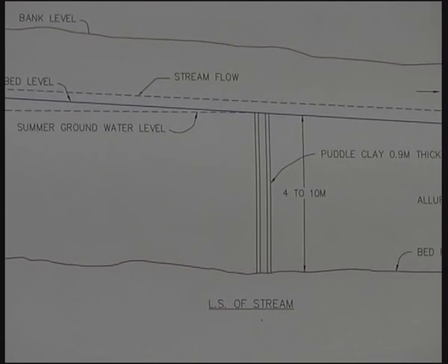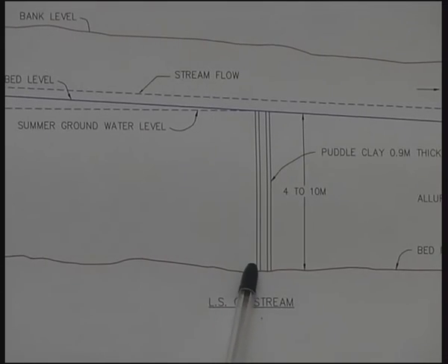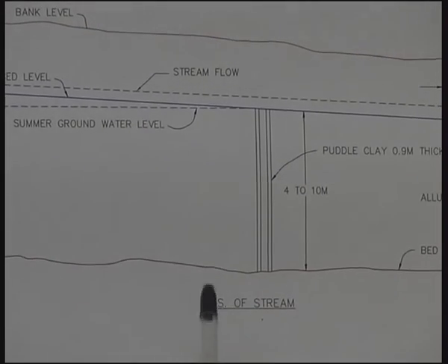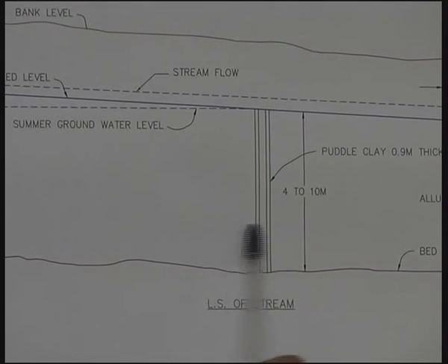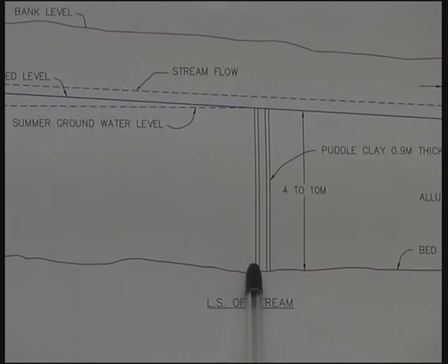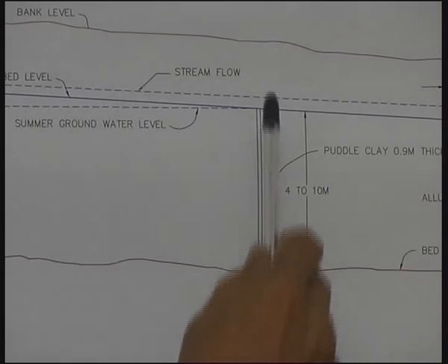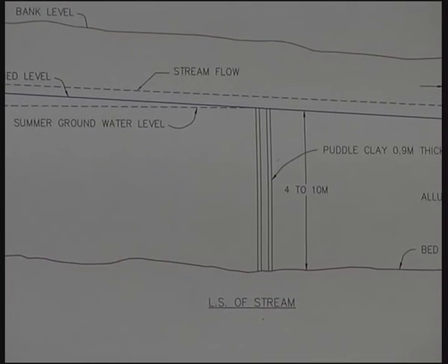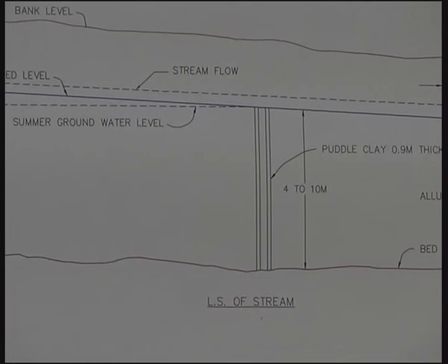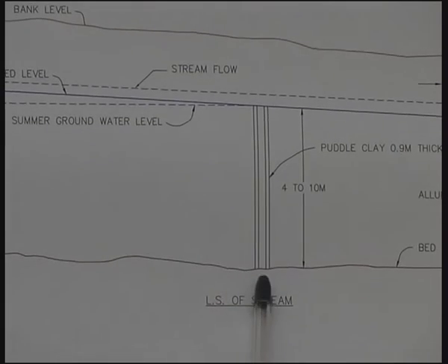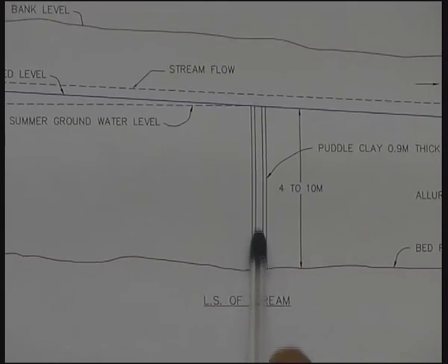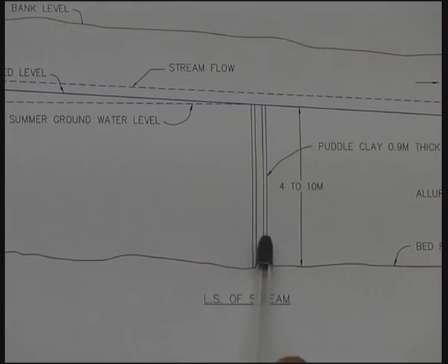It will be colored black, and this film is intended as an additional safeguard to prevent flow of water from upstream to downstream. Now here 2 films are provided on either side as a safe precaution in ensuring that no water flows through. The real thing that prevents the flow is the puddle clay. The 2 films are in addition to the puddle clay,